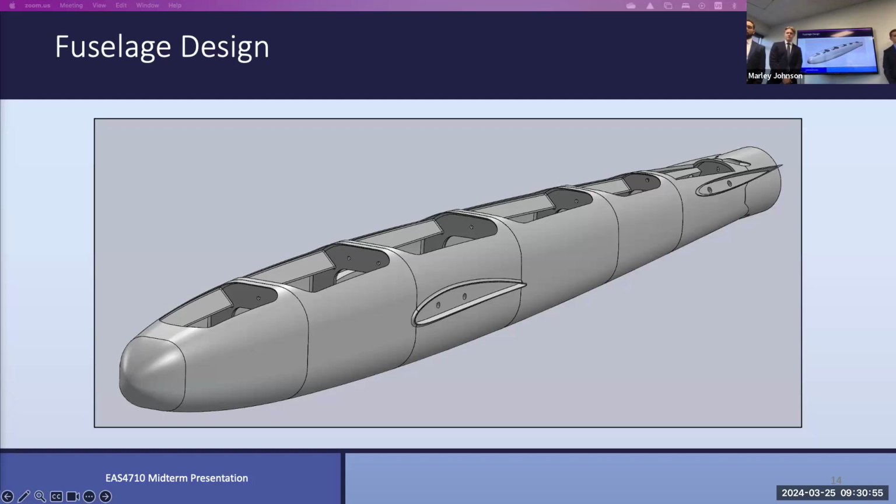And the other thing, I am not even concerned right now. Well, I will see. You probably did a lot of analysis, but I will see in the test flight. But I'm not concerned now. It's a CG. Right now, your tail part, because your motor is here, and also because you want to mount the motor here, you make this one extra thick. So this one is heavy. Here is heavy. And we want to make the CG light around the wing. It might become a problem.